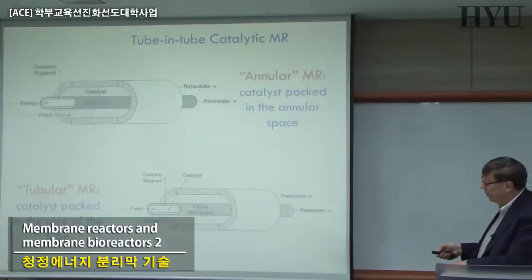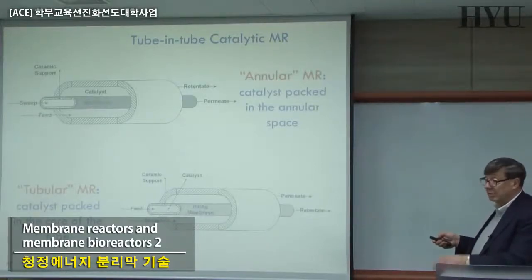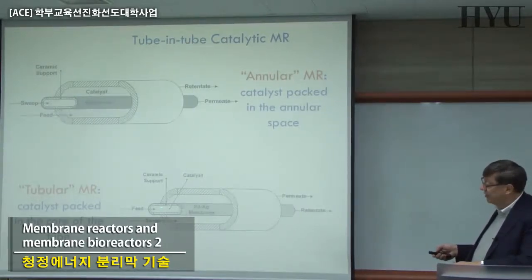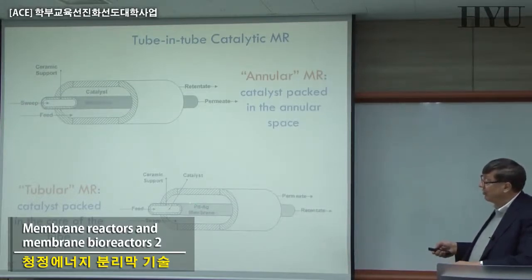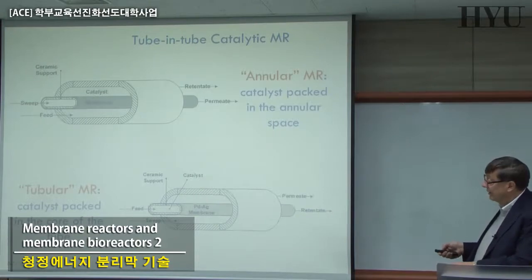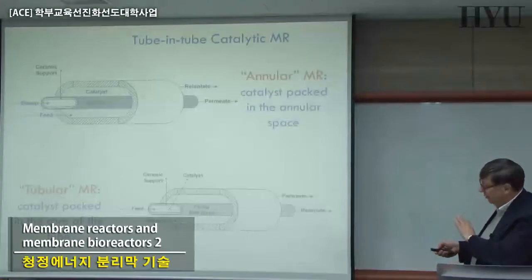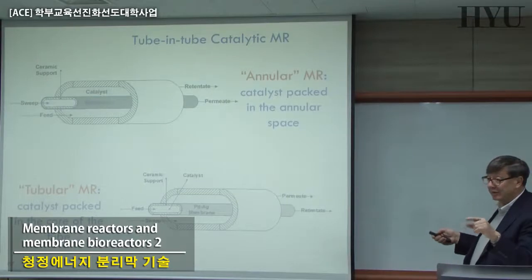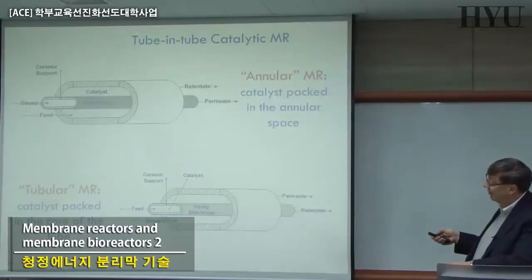You can have another way of doing it, in which the catalyst, instead of being compartmentalized between the vessel and the tubular membrane inside, can be just the membrane itself. The membrane itself can be the catalyst, or the catalyst can be just inside the tube. So basically the feed is not going in the annular system between the vessel and the tube.